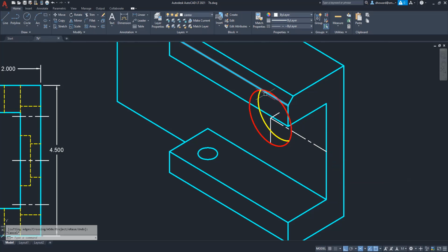Okay, so you can see how that is the inside edge of the counterbore surface. On this same surface, at the endpoint of that 0.313 is the beginning of the 1-inch hole. So that is also the center point of the 1-inch hole.